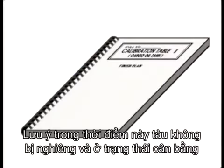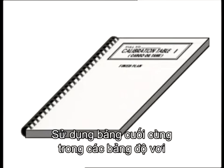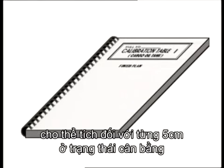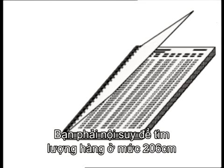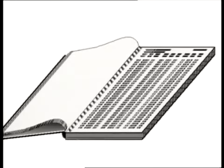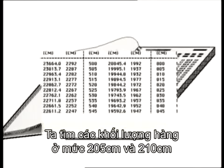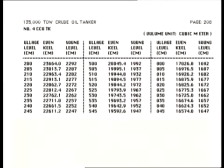Remember for the moment that the vessel has no list and is on an even keel. Use the tables at the end of the ullage tables, which give you volumes at every 5th centimetre at an even keel. You have to interpolate to find the volume of 206 centimetres. Find volumes at 205 centimetres and 210 centimetres.